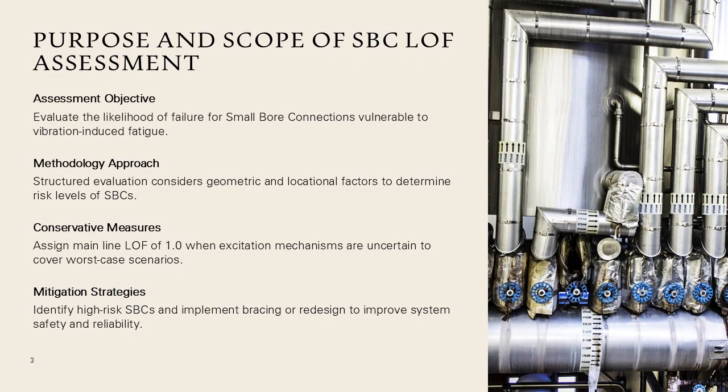The quantitative SBC LOF assessment methodology, as outlined by the Energy Institute, is designed to evaluate the likelihood of failure, LOF, for smallbore connections, SBC, in pipework systems. These connections are particularly vulnerable to vibration-induced fatigue, which can lead to catastrophic failures if not properly assessed. The methodology provides a structured approach to determine the risk level associated with each SBC by considering both geometric and locational factors. The assessment can be performed independently or in conjunction with mainline LOF evaluations.